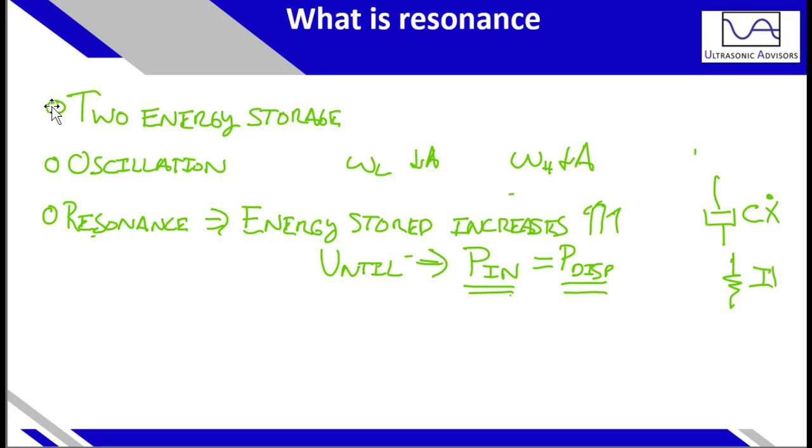So as these values increase, the power, I squared R, is going to dramatically start to increase until these two are equal: the rate that you're putting in power and the rate it's being dissipated. And that's when you peak out. So when you're decreasing your dissipated energy, let's say you're using really good lubrication, you will be able to achieve a significantly higher level of oscillation.